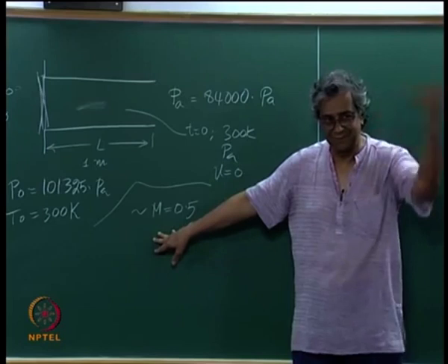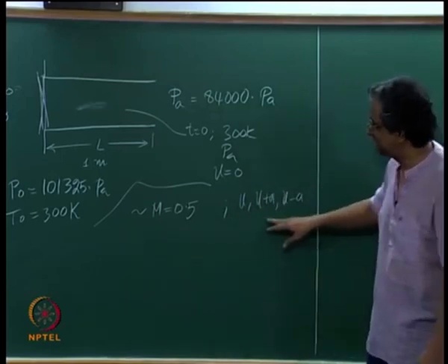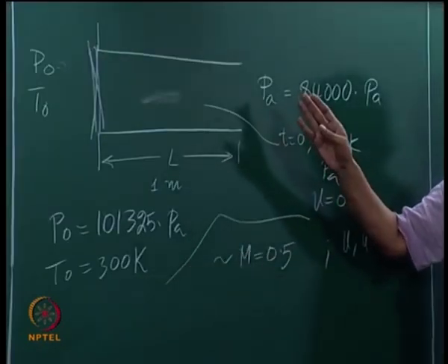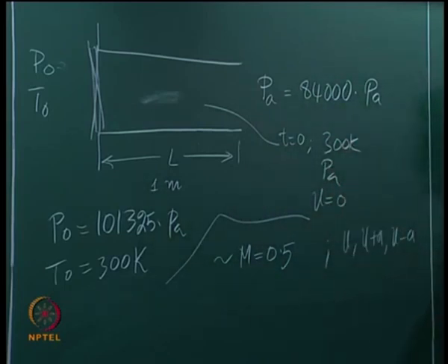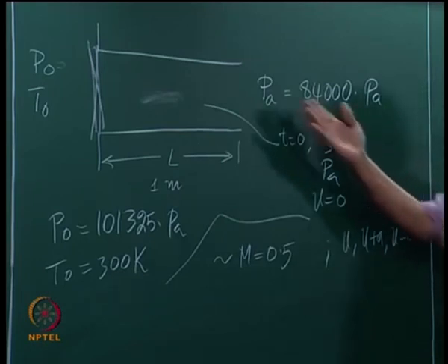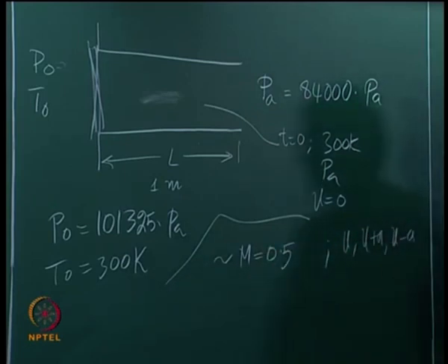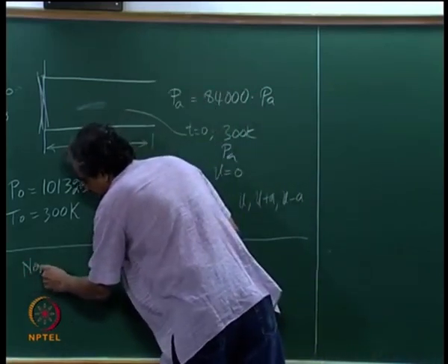So you have to ask the question, why did he not do Mach 2, why did he do Mach 0.5, okay, is that fine. Then you can fiddle around with these just to figure out how the code behaves and see what happens. Am I making sense? For various values, normally, your experience, my suggestion, you may do this, everything is in dimensional form. Normally what you should do is you should non-dimensionalize the equation. Whether you implement it this way and then later non-dimensionalize the equations is up to you. So use the non-dimensional form of the equations.